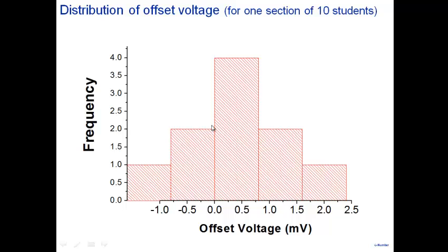And so you can't say, is this correct? As long as you don't measure 100 millivolts. If you measure 100 millivolts, there's something wrong. But if somebody is measuring 2 millivolts, somebody is measuring -2 millivolts, somebody is measuring 5 also. Maybe if somebody is very lucky, very close to 0, that may also happen. That you have a device and you keep on adding and you're saying, sir, I'm not finding any voltage at the output. It's quite possible. Either you're making an error, or it's quite possible that your op-amp doesn't have any offset voltage. That's also possible. That is very, very small. It may be a few microvolts. That's also a possibility here.